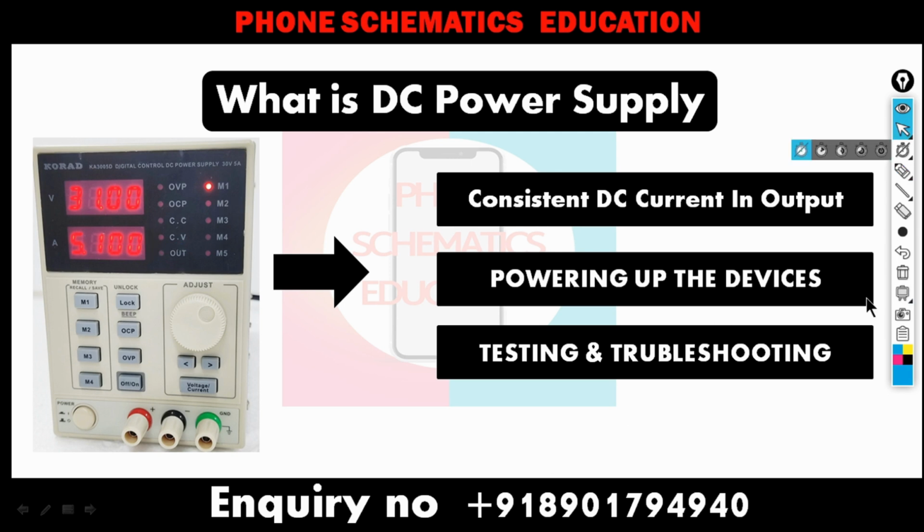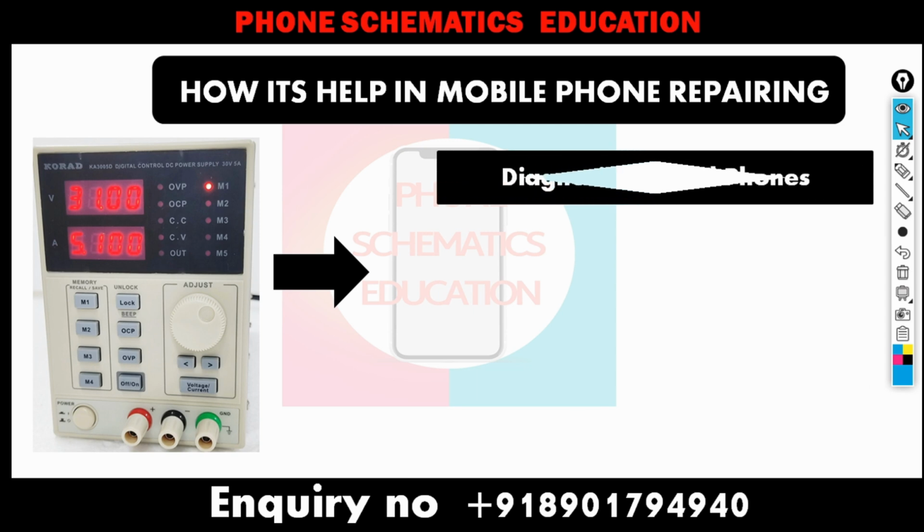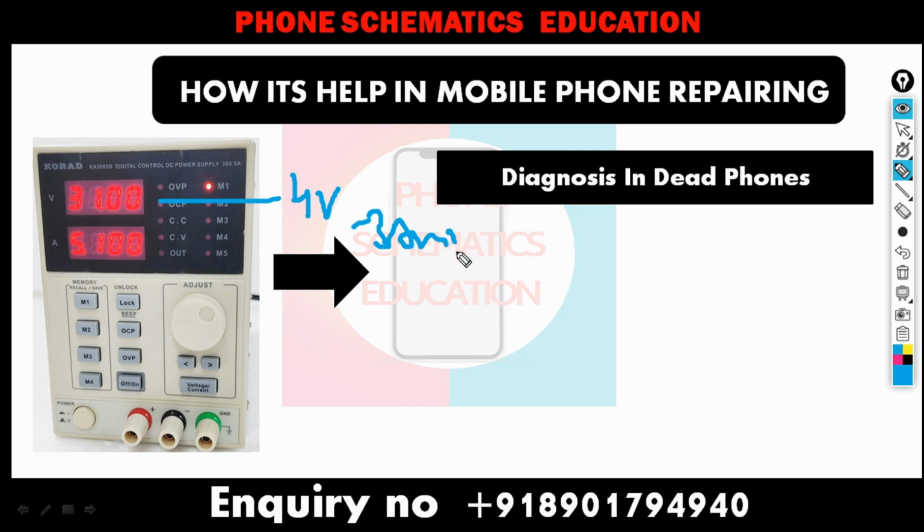Now next, how does a DC power supply help in mobile phone repairing? Now first point, diagnosis in dead phones. When you connect the DC power supply with controlled voltage and controlled current, for example 4 volt and 3 amp, right? When you connect a DC power supply with this current to the mobile phone motherboard, it helps the diagnosis.